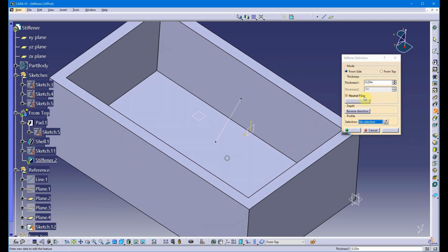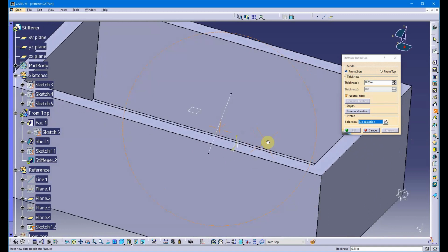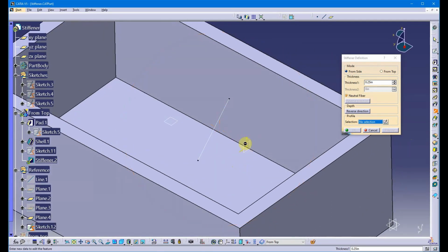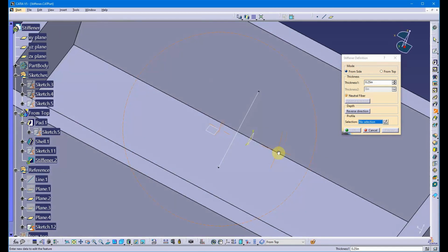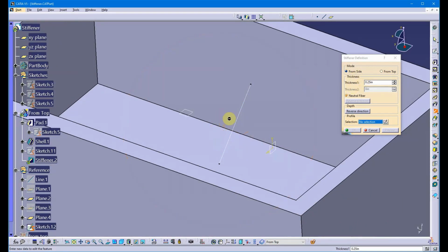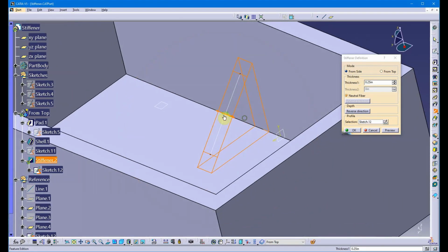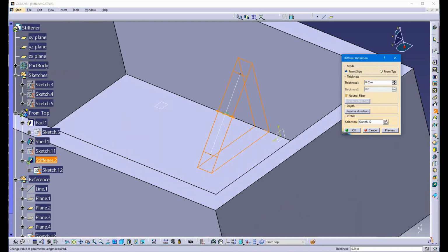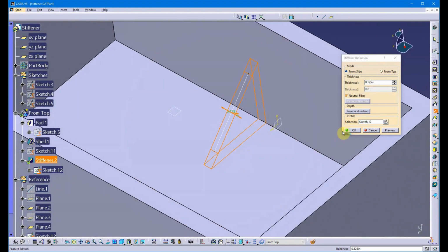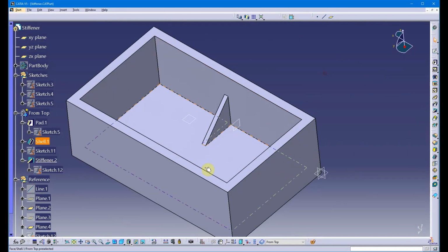So remember, from the side it's parallel to your sketch plane. The extrusion is parallel to your sketch plane, which is different from what a pad would be, which is normal to your sketch plane. So here's my sketch plane. So just imagine from the side is going to run parallel to that sketch plane. So I'm going to do from the side. Notice it merged in down to the current body. And let's say I want to make it 1/8 of an inch wide in thickness. So it merged ends by default. I got neutral fiber turned on, and there's my stiffener.